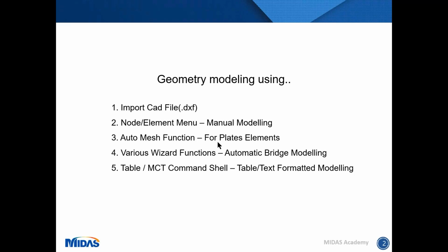Some engineers want to draw the slab using plate elements, which is normally called a shell element. And we have automatic wizard functions. And also, some people like to model the bridges using a table format or the MCT command shell using text format. So I'll try to cover all the functions for today.